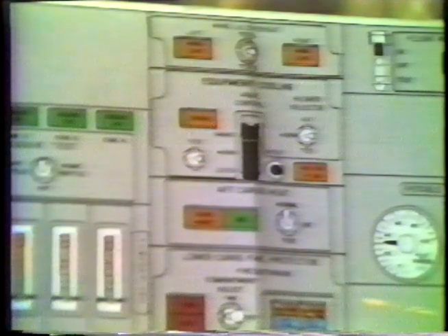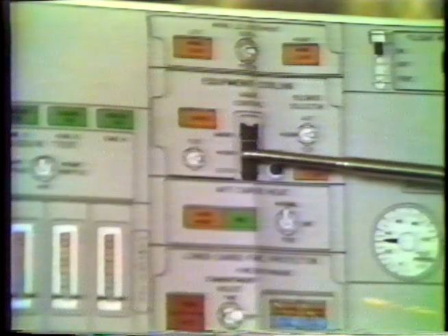In flight, if the no airflow light comes on, it will cut off all air going to the forward cargo and dump it overboard. We have an override switch here controlling this control valve, which is operated by the no airflow light, manually. In a normal position, as I discussed, the air is dumped overboard on the ground, gradually filtered into the forward cargo as the pressure differential builds up.